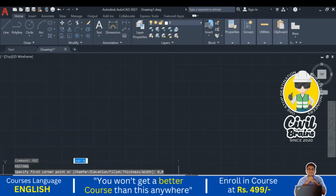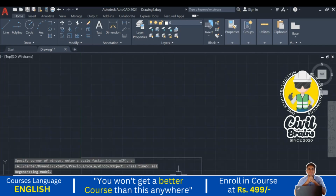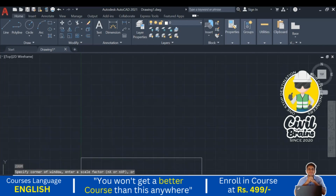The other corner is 420 by 297, enter. The next command is zoom, enter. Then All, enter. Z, enter. A, enter.